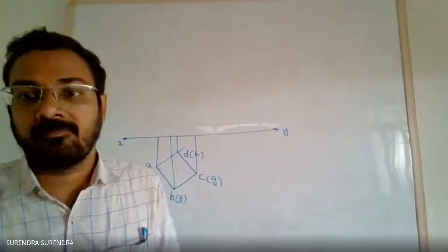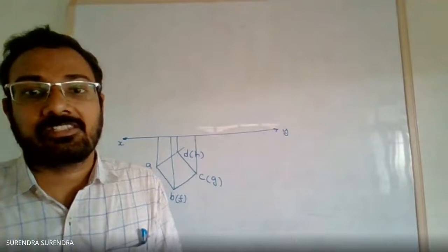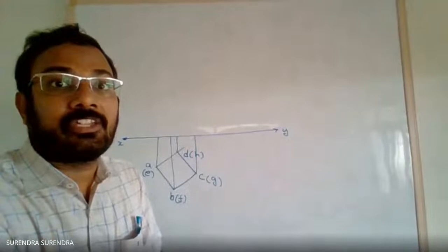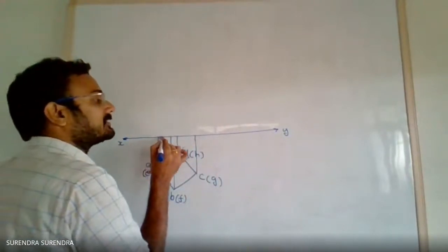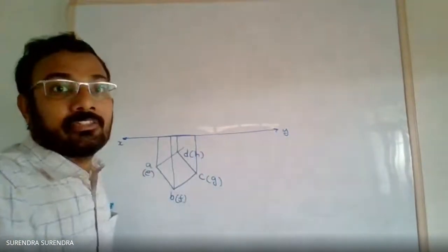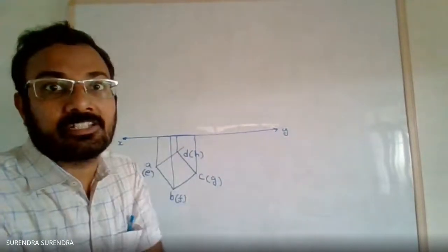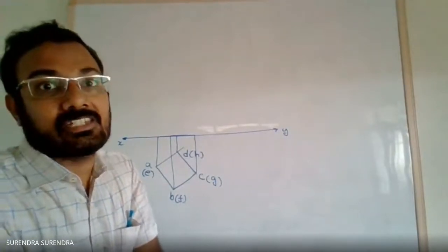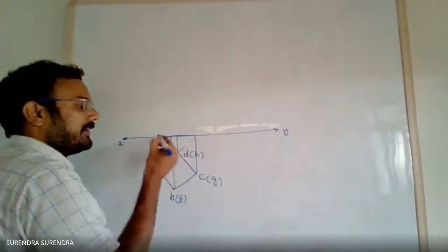What is the condition? It is resting on one of its faces. As it is resting on one of its faces, we should start the front view on the XY line. On the front view, the base must be on the XY line, and from this point the cube must be extended. What is the height of the cube? The height of a cube is nothing but the side length. The side length is given as 60 mm in the problem. So extend each and every side.